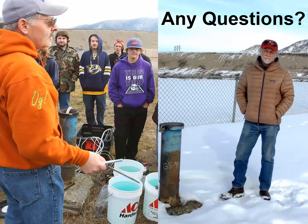And it was the iron in the fittings being replaced by copper, and the copper was soft enough that the fittings weren't holding together, starting to spring leaks. So there was so much copper in the water that it was plating out on the fittings. Anyways, long story short,